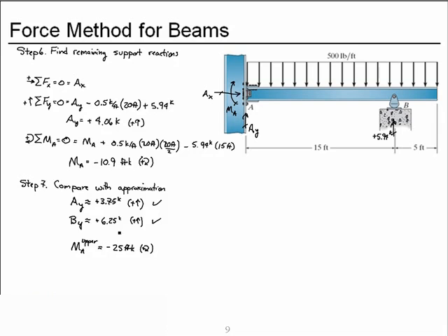So it's less than our upper limit, but still reasonably close, about half the size. So by keeping the roller support or rocker at B instead of out at this far end saves us roughly half the moment at the end. So we'll say that those are reasonably close and that we have a reasonable set of predictions of our support reactions.